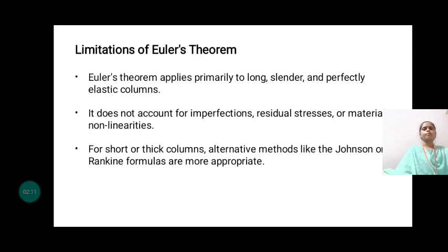Limitations of Euler's theorem. Euler's theorem applies primarily to long cylinder and perfectly elastic columns. It does not account for imperfections, residual stresses or material non-linearities. For short or thick columns, alternative methods like the Rankine formulas are more appropriate.